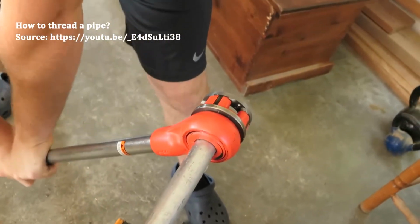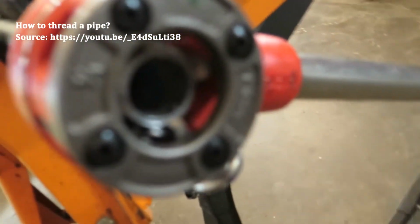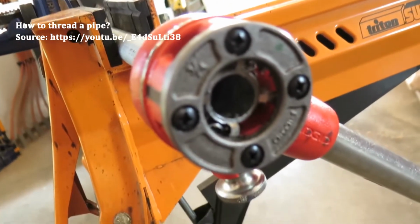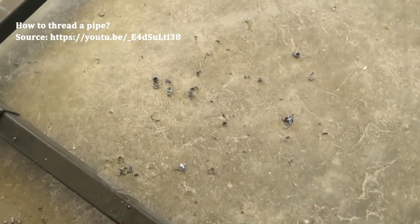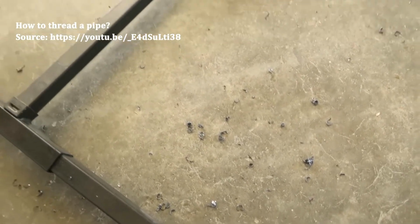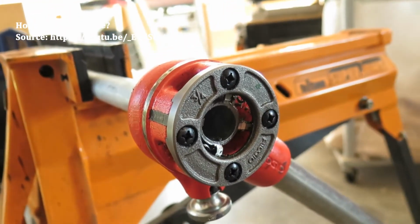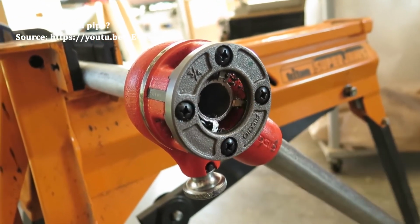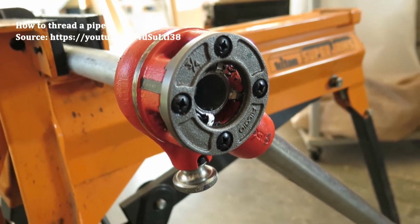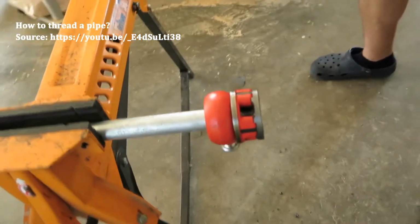Can you just stop for a second there, Roy? So, if you look in here, you'll see that there's some curls of metal. There's lots of them here on the ground too. That's the die cutting the threads, and we're almost as far as we need to go. The pipe should come to the edge of the teeth that are cutting the threads here, and then it's long enough. So why don't you give it another shot of oil, Robert, and then we'll just finish that up.